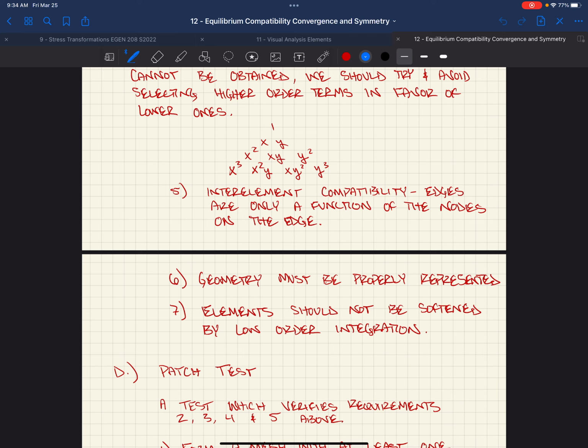I'm just saying there's an assumption you should make that it's a little bit stiffer than it actually is. It is an assumption based on our degrees of freedom and our generalized degrees of freedom. We can't model the actual displacement within a beam because we're limited by the degrees of freedom we have based on the derivation of the element. So we lose a contribution, that's the best way I could put it.